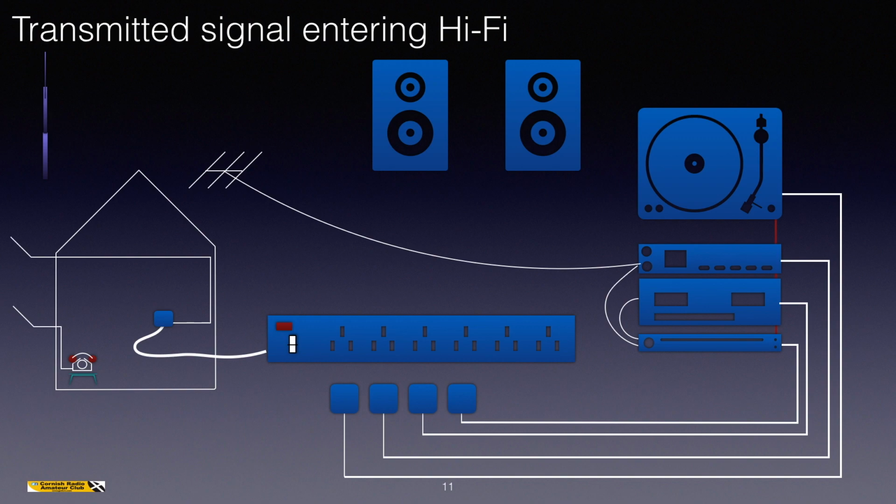The antenna may be sited too close to the house wiring, and then the mains may conduct the RF energy into the hi-fi components, causing a problem.